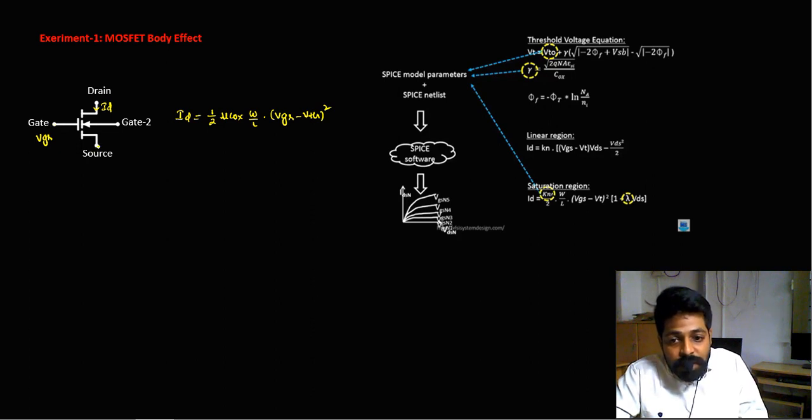So now, the device is connected and some amount of current is flowing, the same ID current flowing across this, around 62 microamperes, which is connected to the load over here. This is my LED, where the brightness of the LED depends upon the current flow. If more current is flowing, the brightness will be more. Because of the 62 microamperes current, the brightness is not maximum.